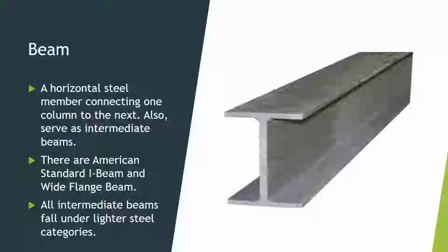The I-beam can be designated with an I or an S. On a drawing, you'll have an I in front of it or an S in front of it. The depth is always exact as it's designated. So if it says 12 inches, that is exactly 12 inches.